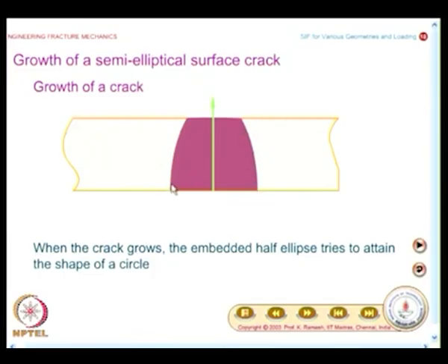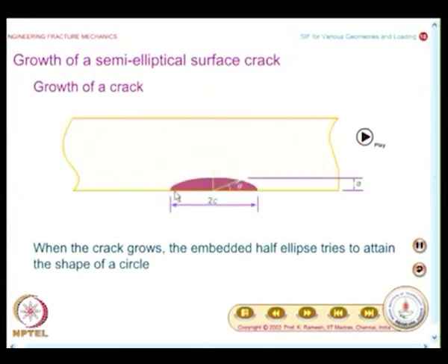The way you have looked at stress intensity factor variation over the crack front and also the fracture properties, what you find is leak before break criterion, if you really play with the design parameters, is doable. This knowledge you would not have got when we were discussing only the through the thickness crack.